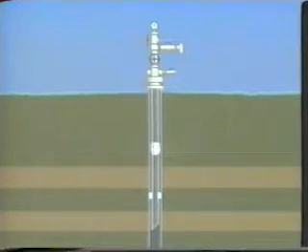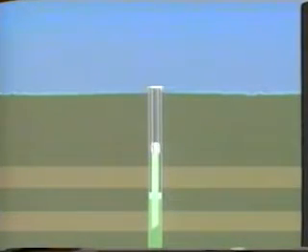Plugs that hold pressure from below only isolate the tubing and wellhead from the formation pressure. These plugs are used to allow removal or repair of wellheads and for safety applications when a well is not flowing but still has the potential to flow. This type of plug usually is designed so that if the need arises, fluid could be pumped through the plug from the surface to kill the well.